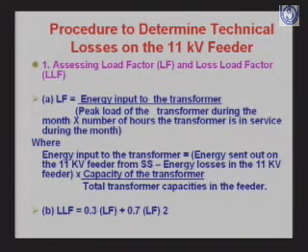This is the total energy received at the distribution transformers. There may be many distribution transformers connected to the same bus, so we take the capacity of that transformer relative to the total transformer capacity in the feeder. This equation can only be used once all the distribution transformers are in parallel operation.